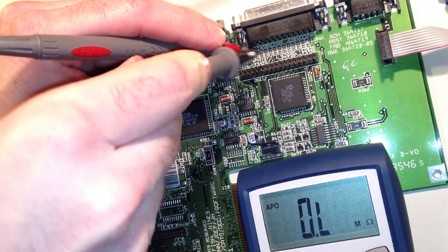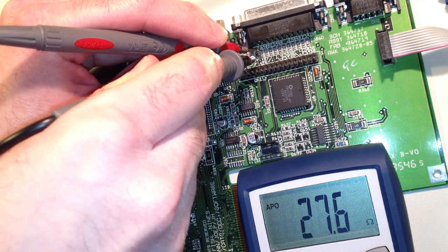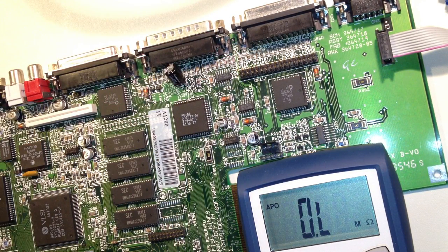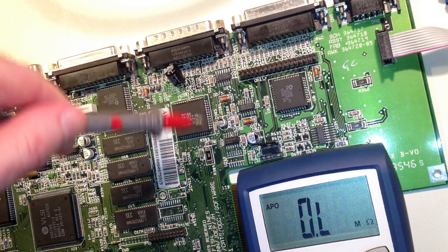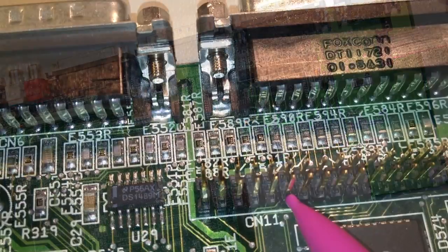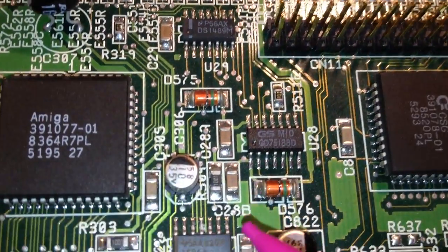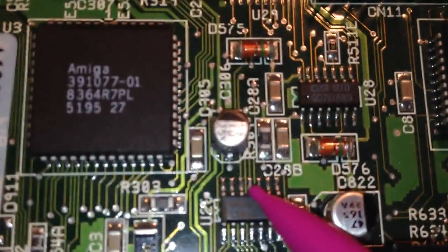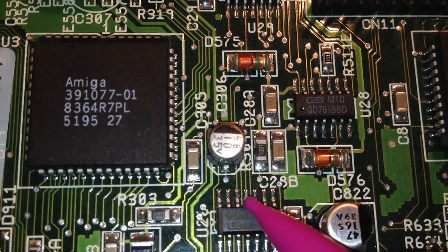So you could just probe the resistor like this also if you want to. And yeah, you can probe here on this chip. So you can easily find out if there is anything wrong with this signal trace here, or if it's the resistor that has blown, or something like that. Now if you do get a reading of 27 ohms between pin 24 here and this pin here, then you could let me know in the comment section of this video, and I might make a follow-up video where I give you some further advice.